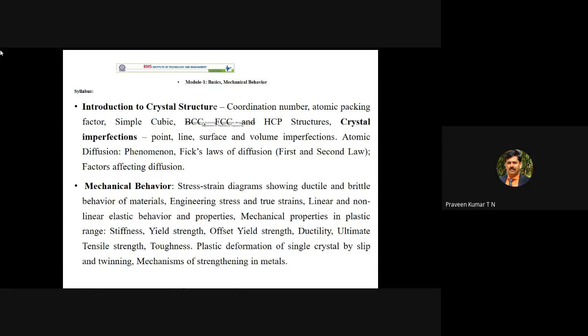Strictly speaking, engineering stress is the force divided by the original area. But when you pull the rubber band, the area decreases. The diameter of the rubber band decreases. That you are not considering in the case of engineering stresses. You have to remember that throughout your 4-year course, most of the time you are considering only engineering stresses. There is one more type of stress, referred to as the true stress.